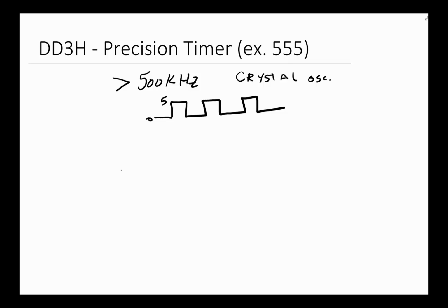We all get synchronized to either when it goes up or when it comes down, and all the circuitry is designed such that it performs its task precisely on the assigned side of the clock, either on the rising edge, where the clock is going from 0 to 5, or on the falling edge, which is when it's coming back down.